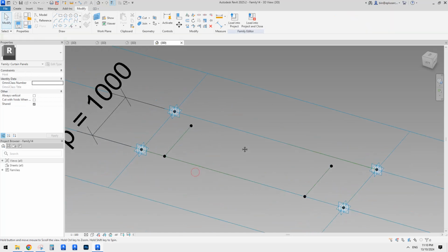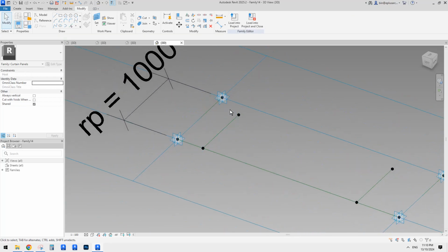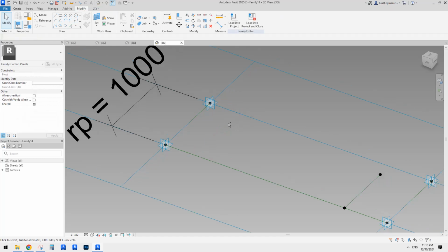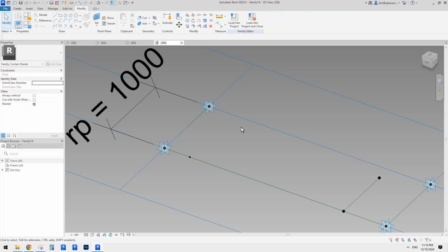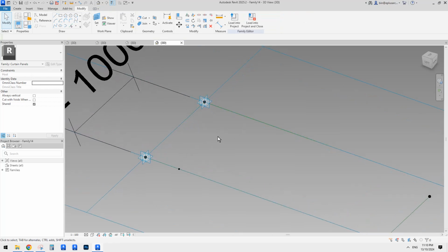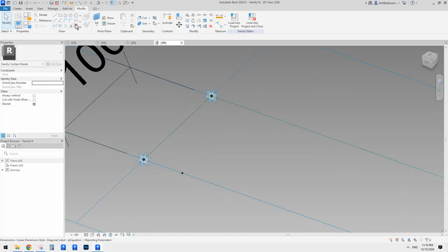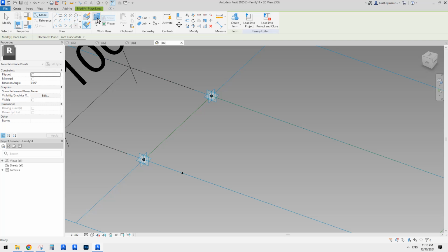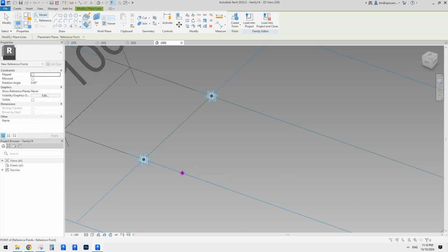I'll just delete this. Yeah, that's fine. Let's just delete. Oh, not delete, maybe dissolve. The difference between dissolve and delete is when you delete, you also delete all those points. When you dissolve, you delete the reference only. You keep the points. So place a point. Place this one. Set work plane, Tab, and place a point.